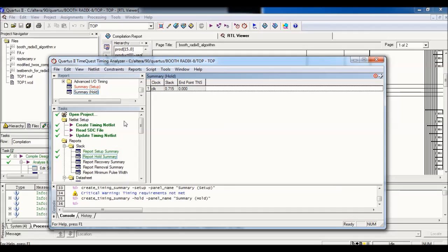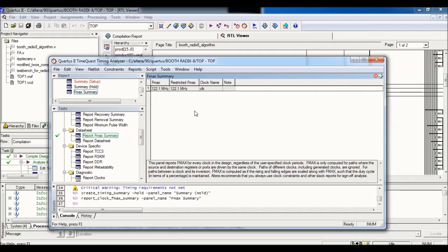And as you can see, there is a maximum voltage and the clock signal frequency which is generated. One of the main characteristics which we can check is Fmax. Fmax is the highest frequency in which our circuit runs. As you can see here, 221 MHz is the highest frequency this circuit can manage to work under. Often it is reduced further due to other delays, but as per our synthesized circuit, there is no such reduction.